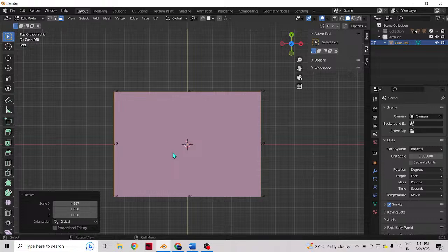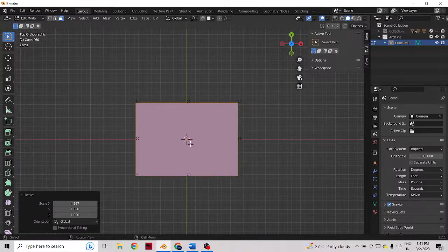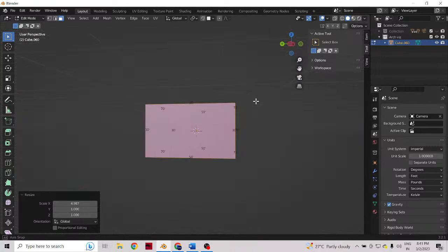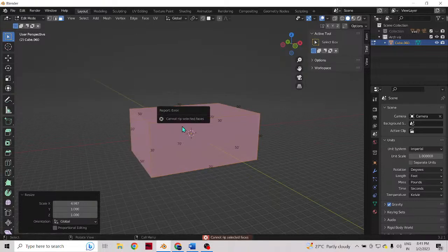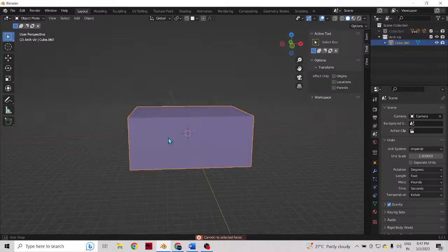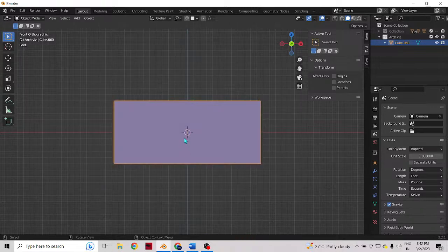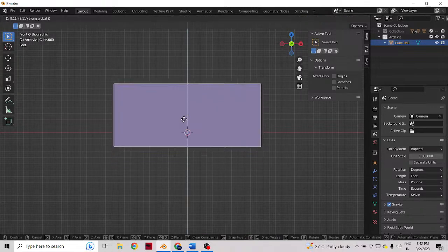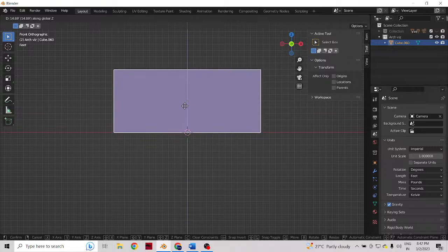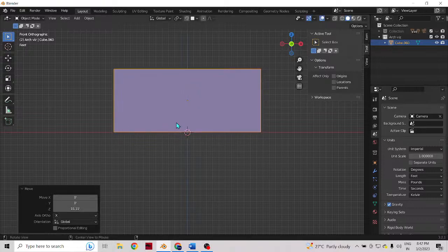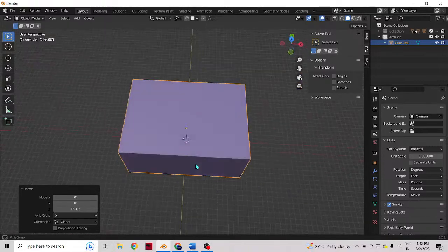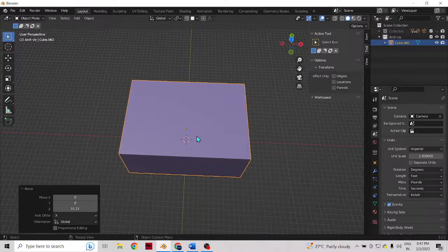Yes, so I have made it 70 feet. Okay, so now this is how my building looks like. Whatever I am creating, I can create within this building. Maybe if required, I can also go to the front view and grab it in z-axis and place it on top of this world origin to make my work a bit easier. Okay, so now this is the outer structure of the building. From here I can handle whatever I want.